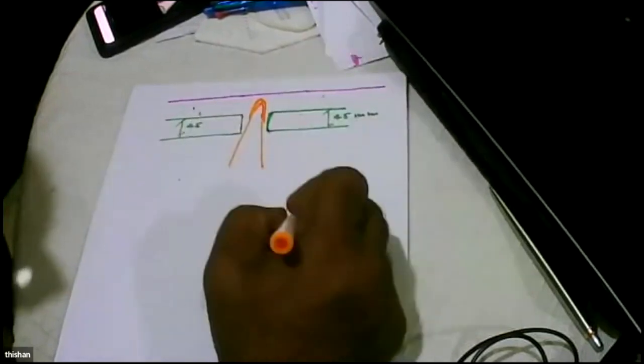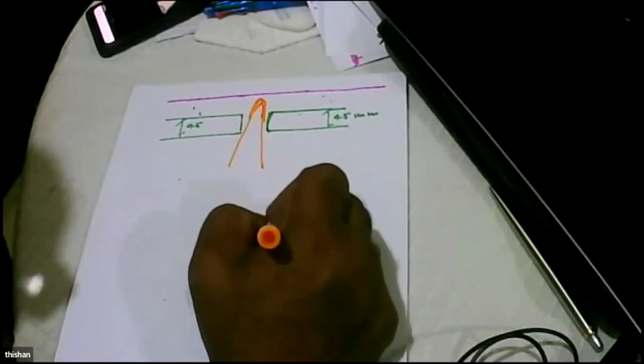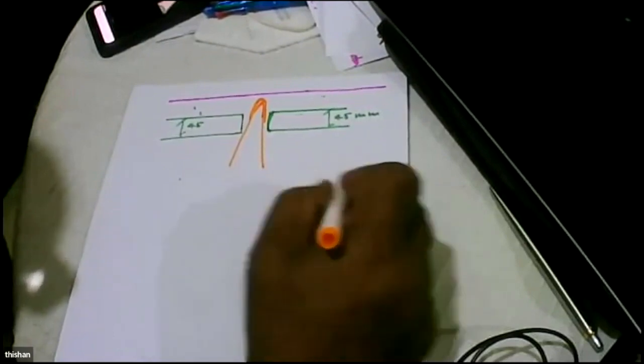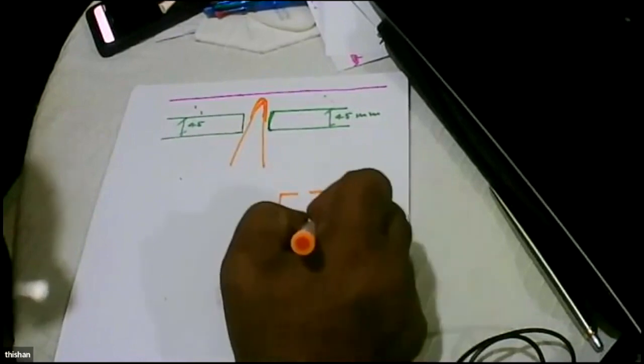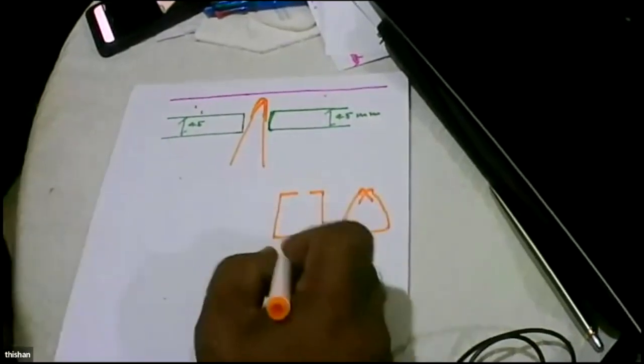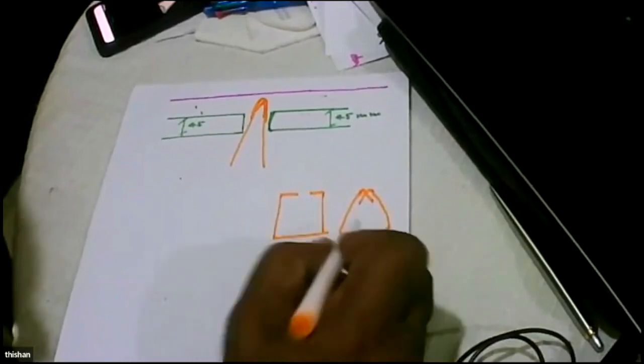And then going like that. Then some reinforcement coming like this. So we bend it. So how we make that reinforcement is we bend a reinforcement like this. Then we convert it to this shape. First we bend it in the bending machine this way. This is what you get from the bending machine. At the side we convert it to this shape.